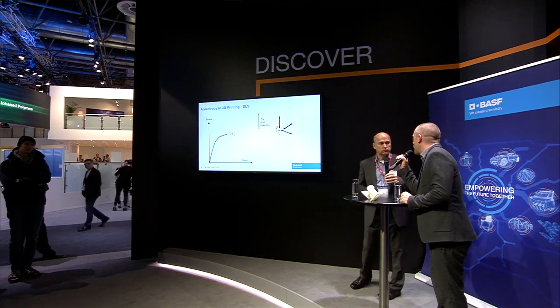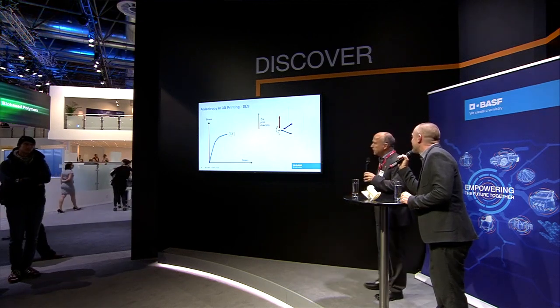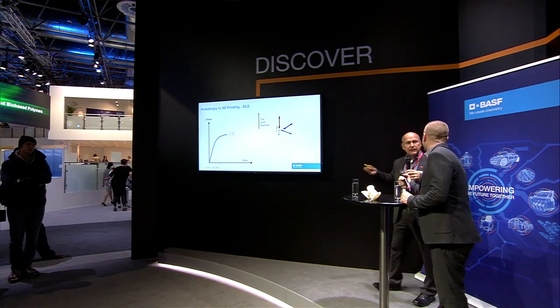And this is sometimes a little bit of a curse, because if you look at the part and you think you see some ribs, as in injection molding, then you should forget about those ribs, free your mind and say, okay, we do some reinforcements, but they do not necessarily have to look like ribs. So it's free your mind, but also free your model, huh? Yeah, it's basically using the better design freedom that you have in 3D printing.